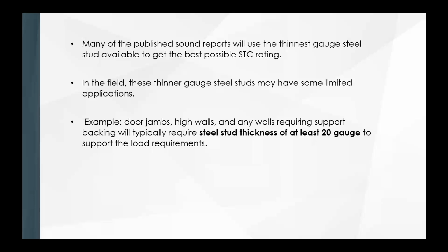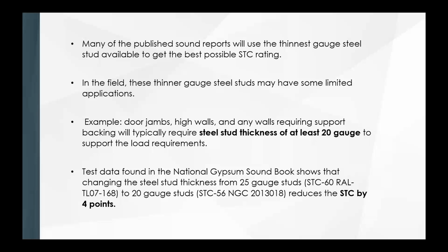So you've got to be mindful of that. Examples: door jambs, high walls, anything requiring backing. It's going to require thicker studs, 20 gauge at least, for the load requirement on that job. Okay, so let's just go apples to apples with the stud thickness.